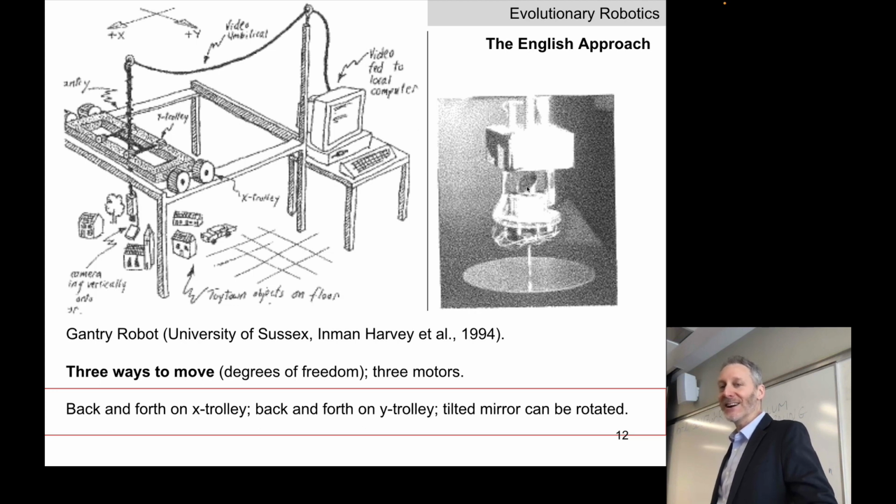Last little detail here. Just underneath the downward pointing camera, they placed a small circular dental mirror. This circular dental mirror was attached to a motor that would rotate this angled dental mirror around and around and around. So basically, the robot is looking upside down underneath the table, 360 degrees around itself horizontally.